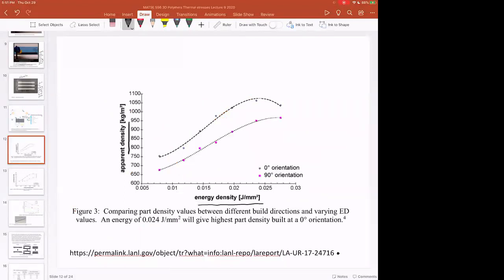If we put more energy into the powder, we get more and more densification, and a higher apparent density, up to the bulk density of the pure polymer, on the order of about 1,000 kilograms per meter cubed, or about 1 gram per centimeter cubed. For polyolefins, a little less. Nylon is about 1. So this is close to full sintering, or full densification, as we might call it.